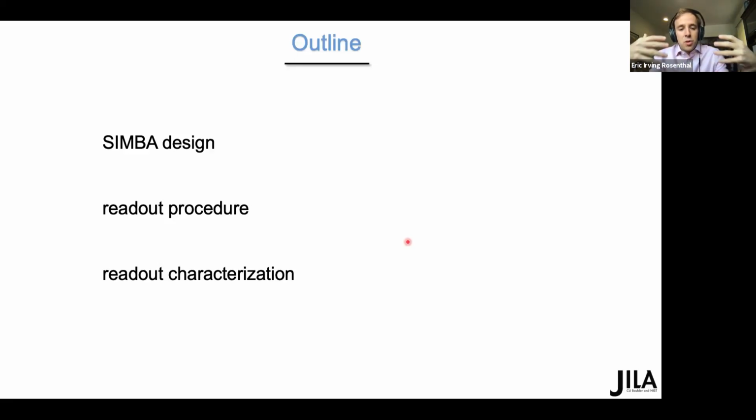But I think there's a hard upper limit by the plasma frequency of the junctions, which is about 15 gigahertz. That's where the junction no longer looks inductive. But below that, you're limited by any filtering you might put in your bias line.